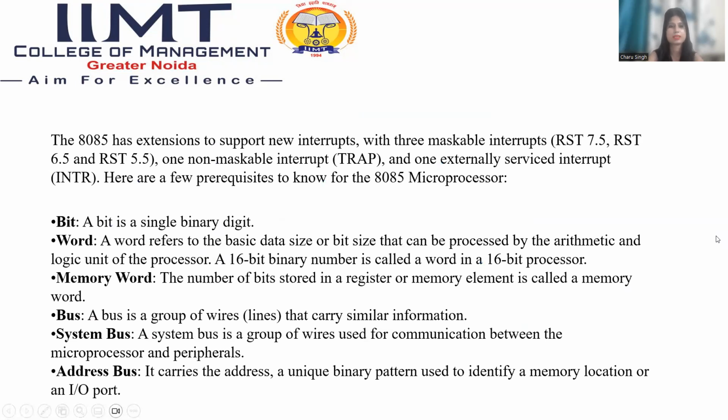The 8085 has extended support for interrupts, with three maskable interrupts, RST 7.5, RST 6.5 and RST 5.5, and one non-maskable interrupt, that is TRAP. TRAP has the highest priority among all those interrupts. And there is one externally serviced interrupt, that is INTR.